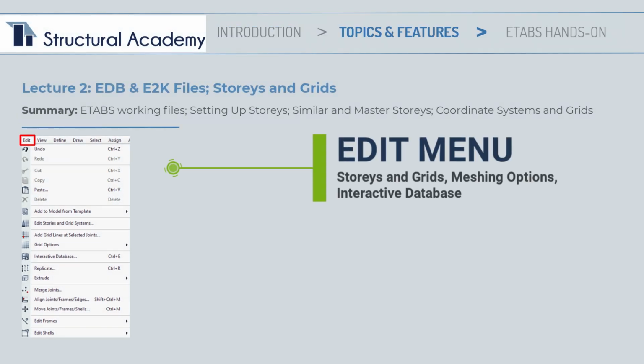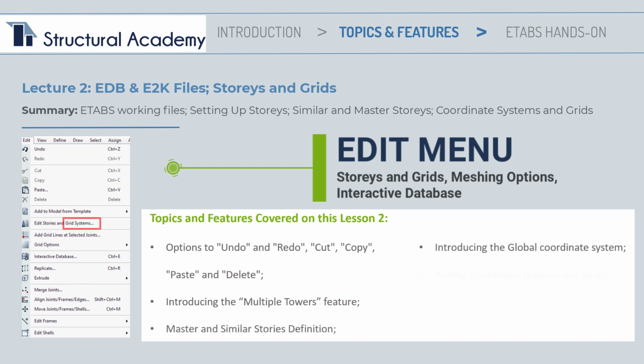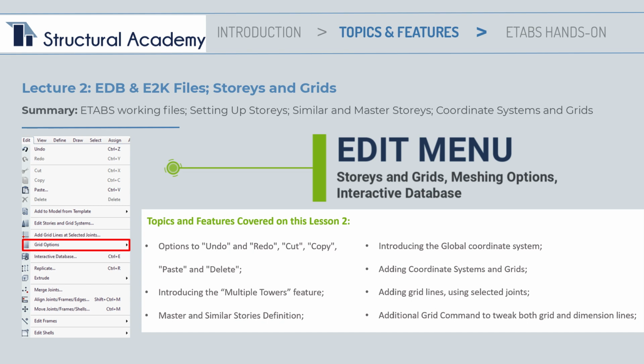Next up on our list of top drop-down menus is the Edit menu. In this lesson you can expect to learn about the following features offered by the Edit menu. Options to undo and redo, cut, copy, paste and delete. Introducing the multiple towers feature. Master and similar stories definition. Introducing the global coordinate system. Adding coordinate systems and grids. Adding grid lines, using selected joints. And revision of additional commands to tweak both grid and dimension lines.